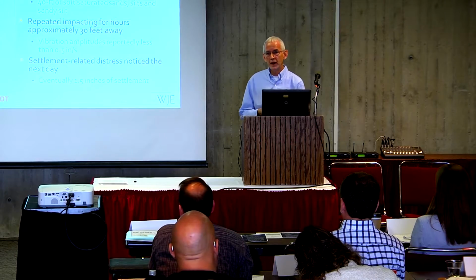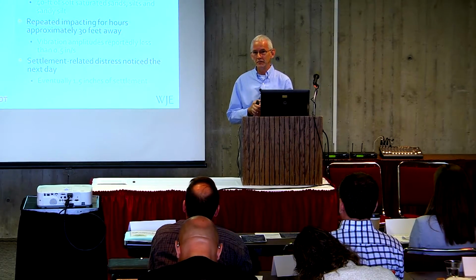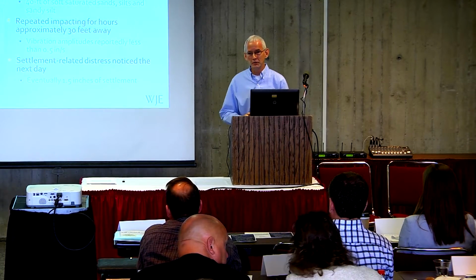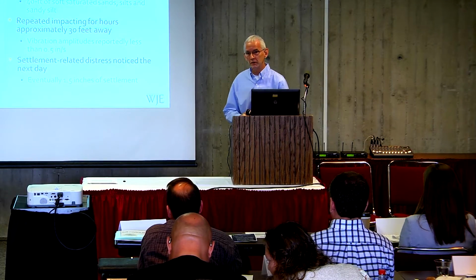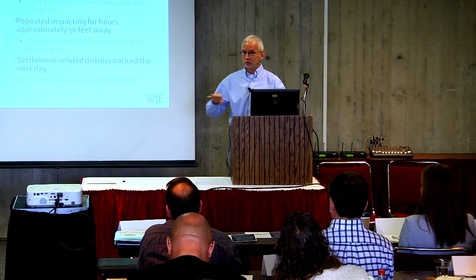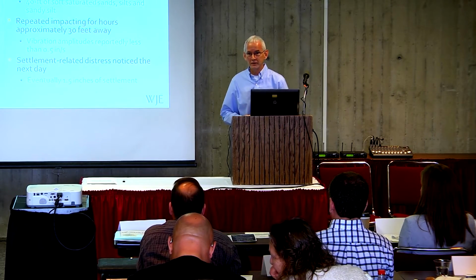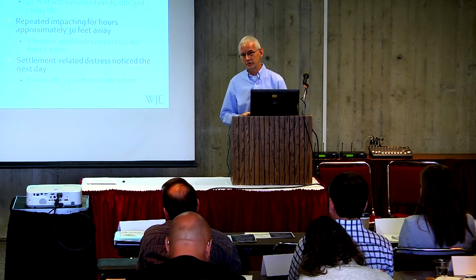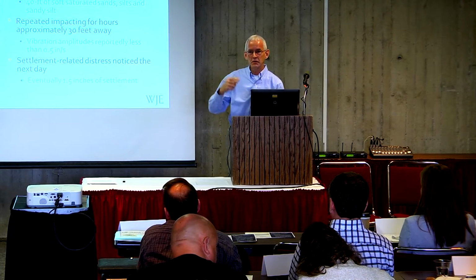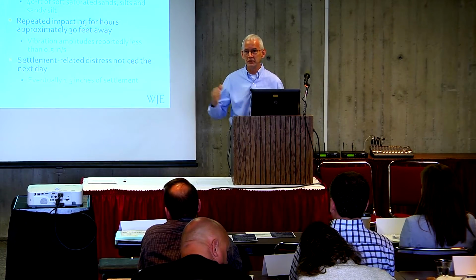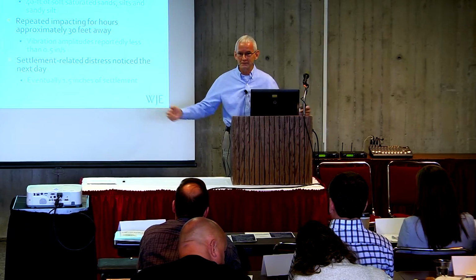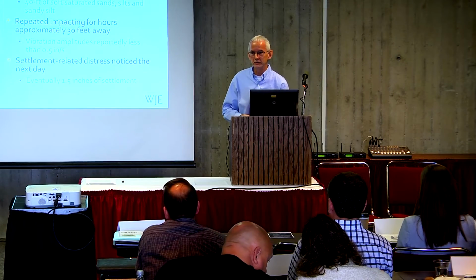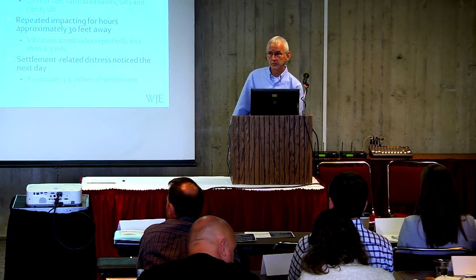If it is saturated, you could even take the soil and saturate it if you want, and use that to help you drive piles into it. But then you're also going to possibly generate some soil subsidence. There's a zone of effect. Typically, they say that range of influence is equal to the length of the pile that you're installing, a radius of influence. At that outer radius, you start at zero settlement, up to the maximum settlement directly adjacent to the pile.